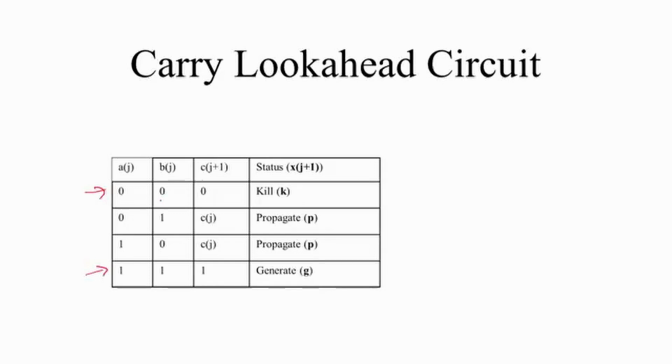That means I call it kill. I kill the carry; I do not allow the carry to go, whereas if one goes then it says I am propagating. So I say I kill. When Aj equals Bj, irrespective of the carry of my stages to the right, the carry I generate for the next stage is 0. So I call that status kill, right.